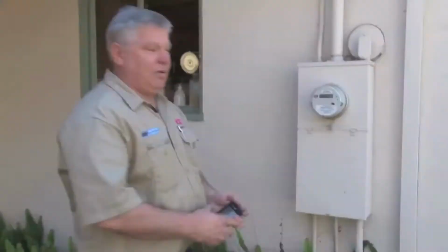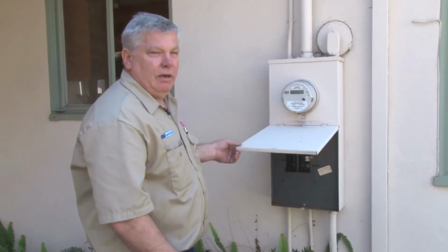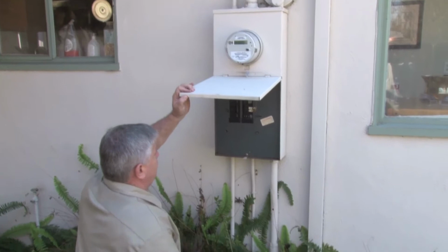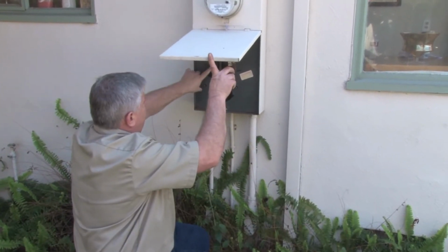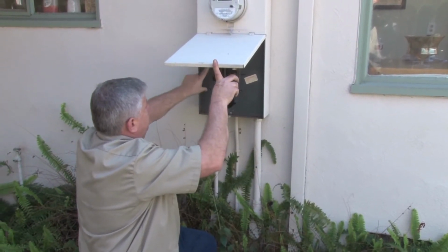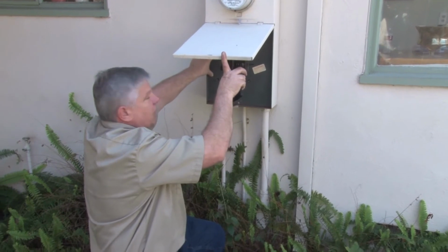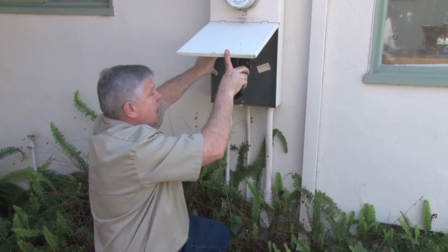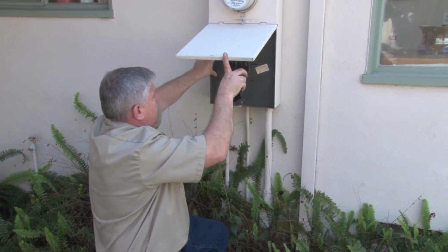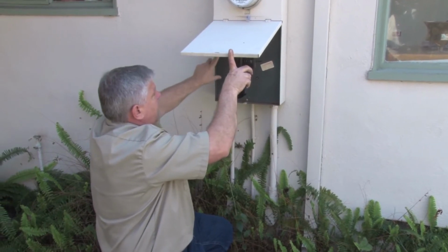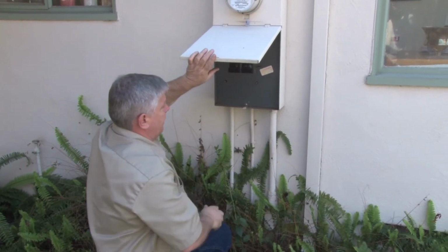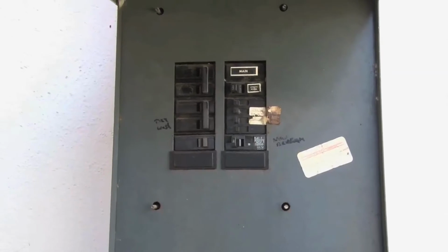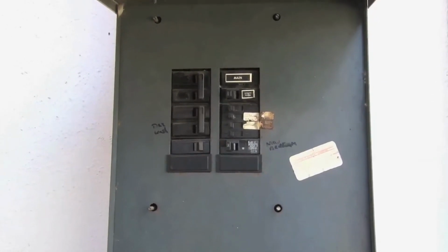First thing we want to do at the electric panel is identify the breaker that goes to the air conditioning unit. I see one here that's 30 amp, but it's marked the dryer and the wash machine, and then we have a 40 amp. There's no other heavy-duty appliances in the house, so for the time being, I'm going to say that that is our AC unit, and we're going to go from there. But while I'm here, I'm going to take a picture so I have record of it, and then we can open it up and find out.